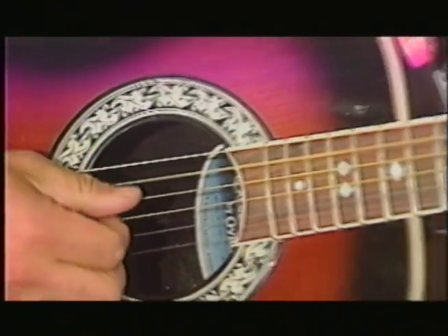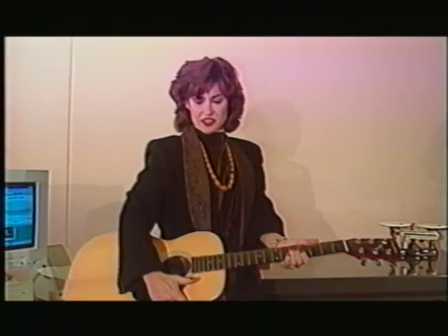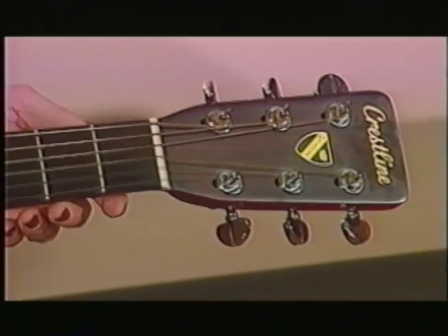Many FEA analysis packages cannot predict the effects of load stiffening when attempting to avoid potentially destructive responses to vibration. Load stiffening occurs when an object, such as this guitar string, is stretched to produce a specific frequency or tone. For example, as I loosen or tighten the string, its tone or natural frequencies will change.